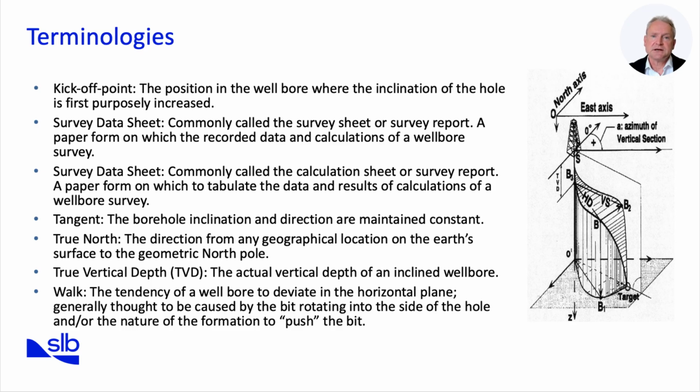Survey sheets are essential during and after drilling. They help confirm that we're on course or alert us when corrective steering is required. Traditionally, these were printed sheets, but now they're digitized and integrated into real-time monitoring dashboards. Drilling engineers and directional drillers continuously update this data to calculate parameters like vertical section, horizontal displacement, and dogleg severity.